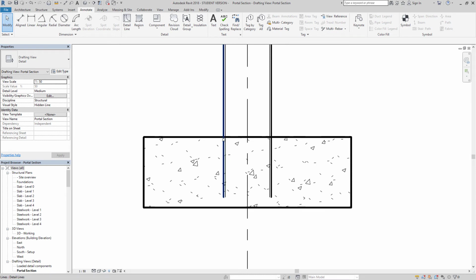and what we want to do first of all is create a gap between the top of the foundation and the underside of the plate that would be bolted to the foundation. That gap is where they would put some grout. It enables the steel erectors to erect the steel frame so that everything's level, because they could put different packers underneath the column and get them all level, and then they pour some grout in there and grout it all together.